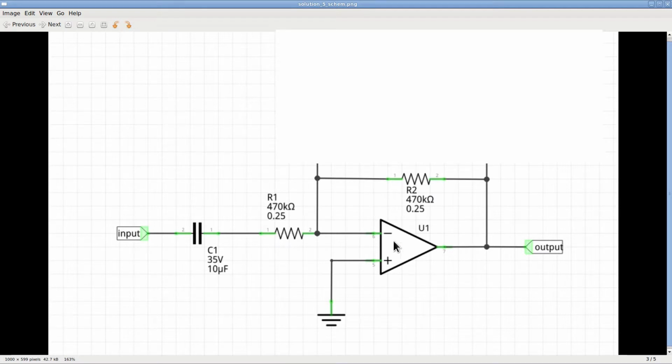Since the gain is 1, whatever we put at the input will be reflected on the output, with the same peak-to-peak value, but upside down, since this is an inverting amplifier. Everything works fine for very low voltages, and we can increase the input voltage up to 5 volts peak-to-peak safely, without causing the output to go beyond that value. However, if we input signals that exceed 5 volts peak-to-peak, we would find the same peak-to-peak signal on the output, and therefore on the auxiliary inputs of the SSI 2130, which we don't want.